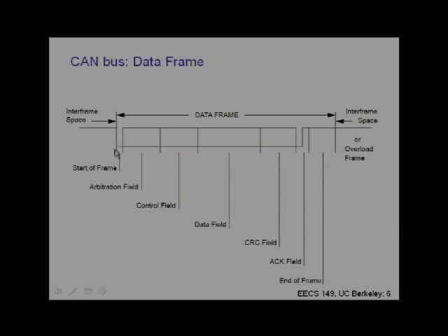First of all, the ECU checks if the bus is idle. There's a signal which tells it if the bus is idle. If the bus is idle, it means nobody else is trying to transmit, so this processor can try to transmit. But remember, there has to be arbitration. The way arbitration is done is that if you have multiple nodes that want to transmit at the same time, they try to write their priorities onto the bus.